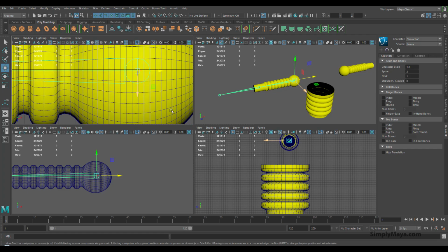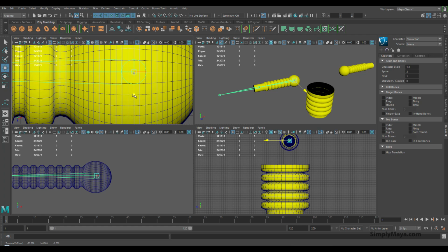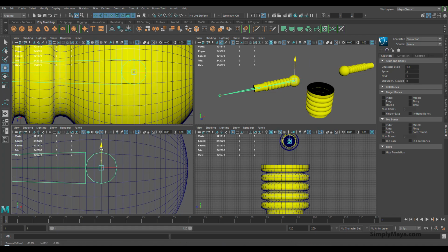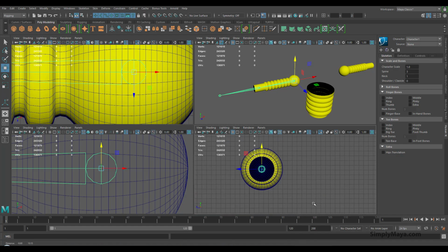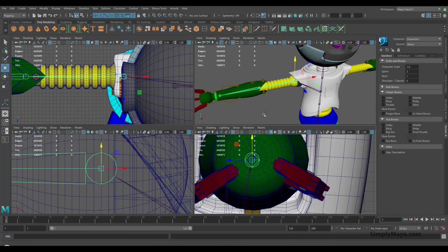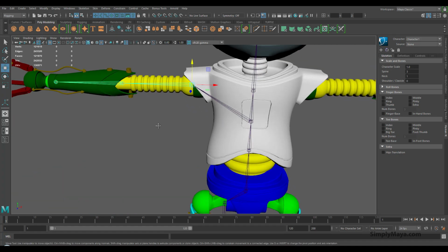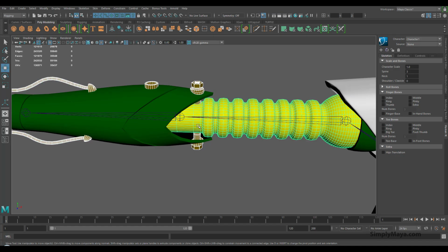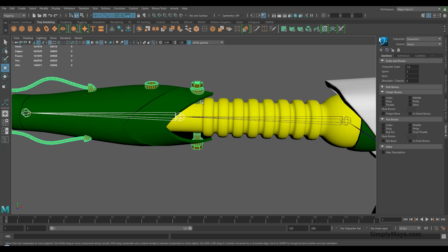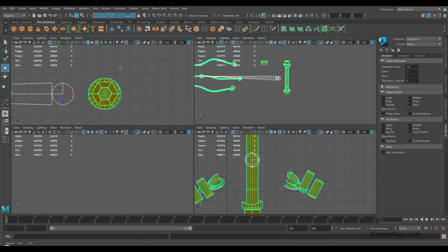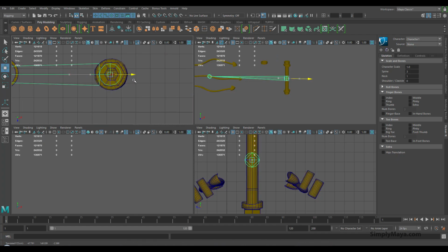Now if you were creating a rig for animation, you would take more time and trouble about placement and everything else. But as we're just doing a very quick rig for posing, we're going to do this approximately, which will be good enough. So that should be everything lined up. It is. And now we can go back to our complete views here and move our next joint into position. So it will be this joint around this bolt. Again, select only the components that you need. So this joint and this bolt, hit Control 1, back into your 4 view, Control 1 in each view, and this will allow us to place this in the middle of the joint quite simply.